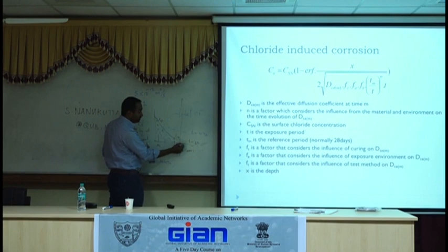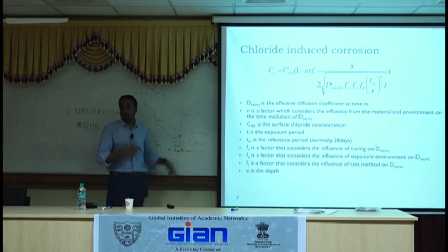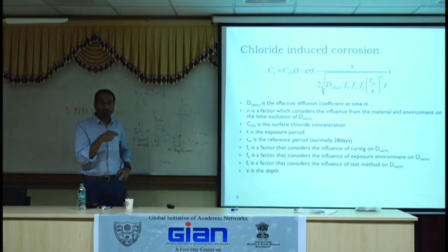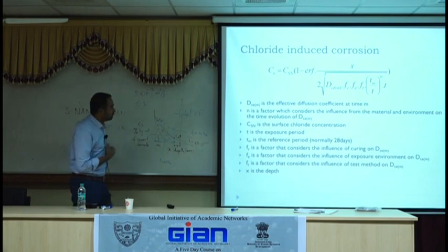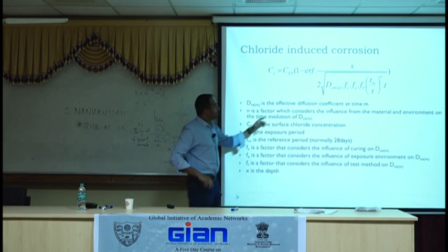If your rebar is here, and this is your threshold, which means T1 is okay, but at T10 the threshold has been exceeded, so you're likely to get corrosion probably in about 5 years' time. It could be 10 years, it could be 50 years, depending on the variables. And that's how you use the graph for your benefit. And this is where I said I'll use the best and the worst case scenario.